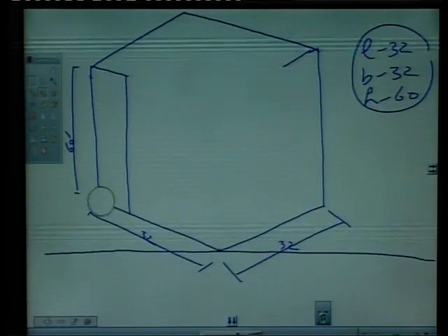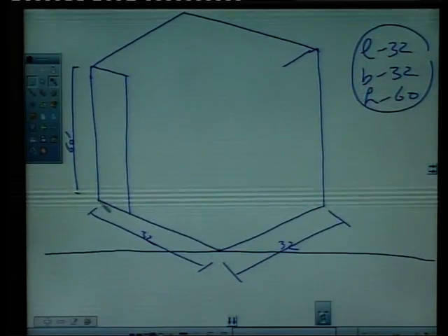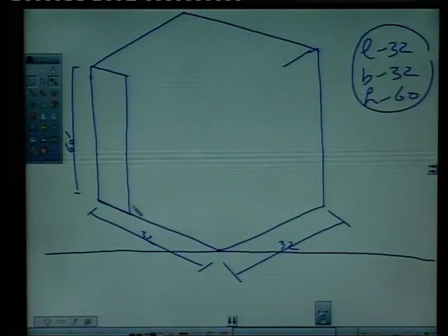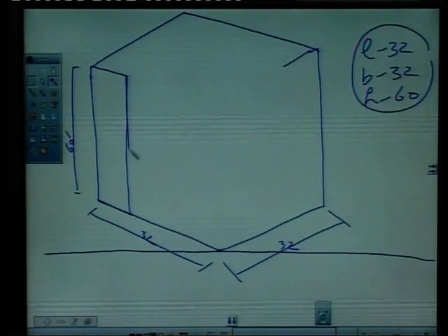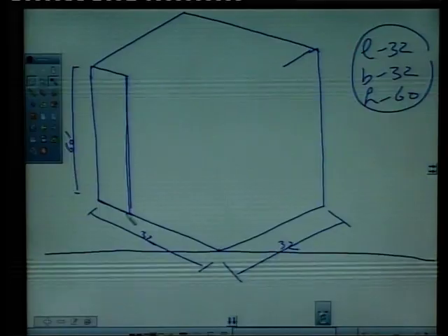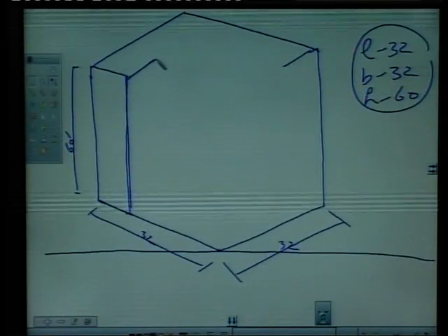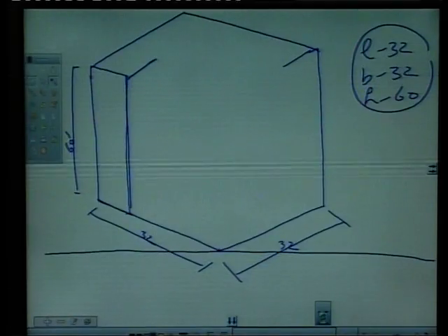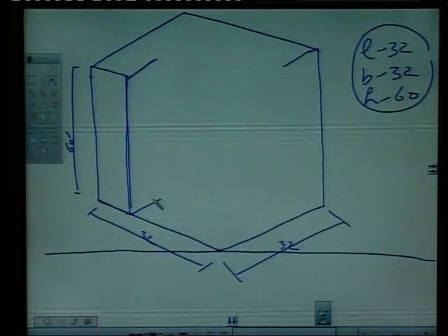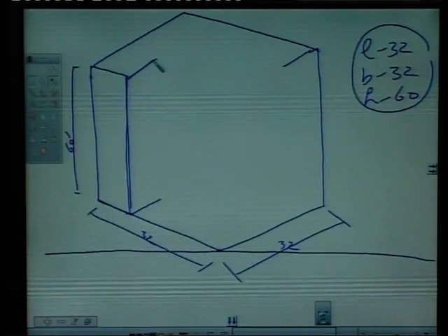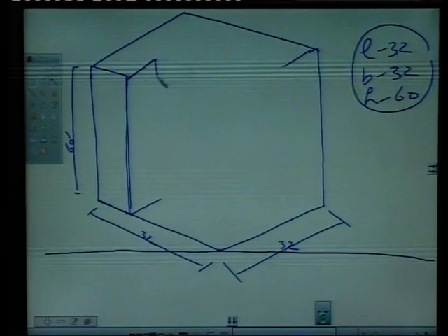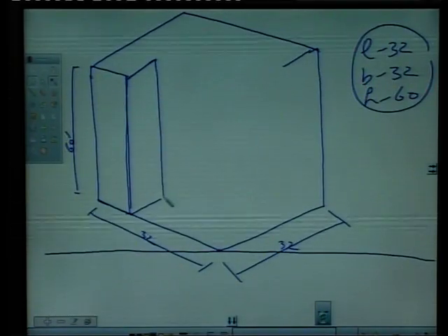Say this is 12, just mark 12 feet and draw a vertical line, right? Then go this way in this direction, a parallel line again at 30 degrees towards right. This is given in the plan, which is say 10 feet, okay? Again vertical lines remain vertical, draw a line like this.